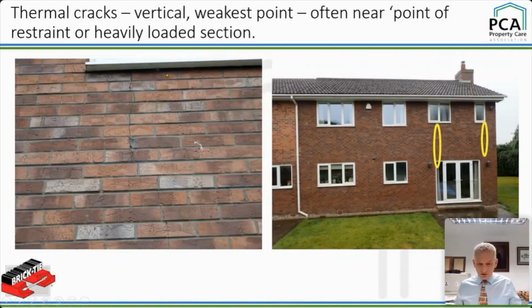This is again expansive corrosion, and we've got, so not expansive corrosion. I'm talking rubbish. I looked at my watch then. We've got thermal cracking, and it's very hard bed joint material, which was not helped, and that's the wall, and it's cracked there. Okay, it's cracked down there.